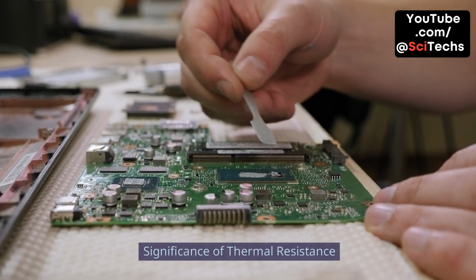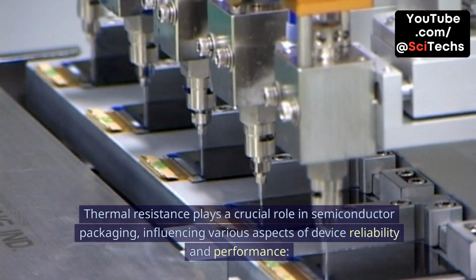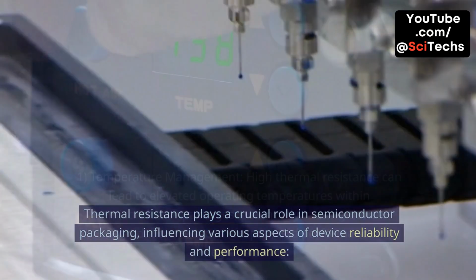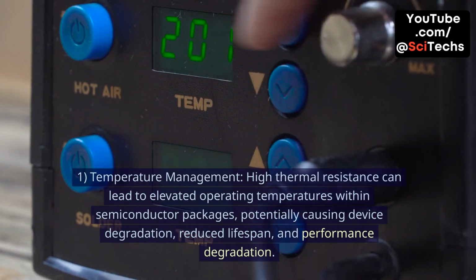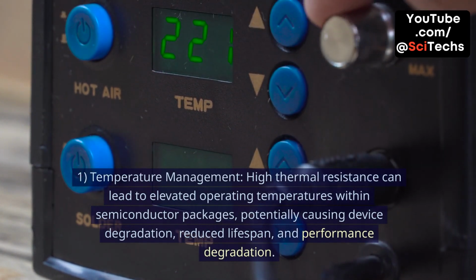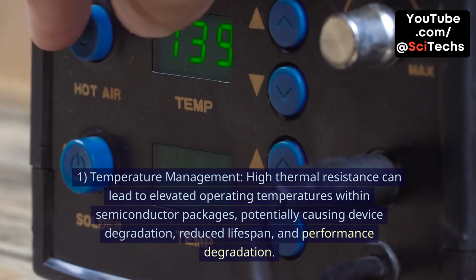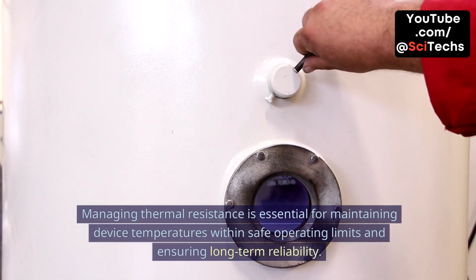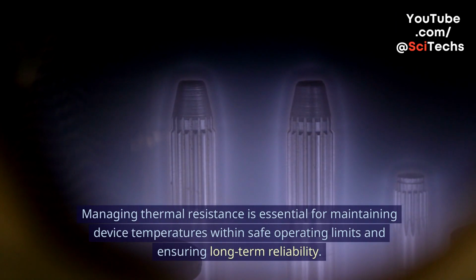Significance of thermal resistance. Thermal resistance plays a crucial role in semiconductor packaging, influencing various aspects of device reliability and performance. 1. Temperature management. High thermal resistance can lead to elevated operating temperatures within semiconductor packages, potentially causing device degradation, reduced lifespan, and performance degradation. Managing thermal resistance is essential for maintaining device temperatures within safe operating limits and ensuring long-term reliability.